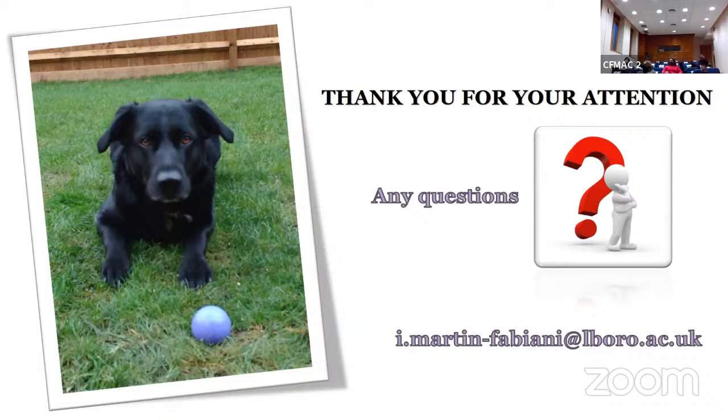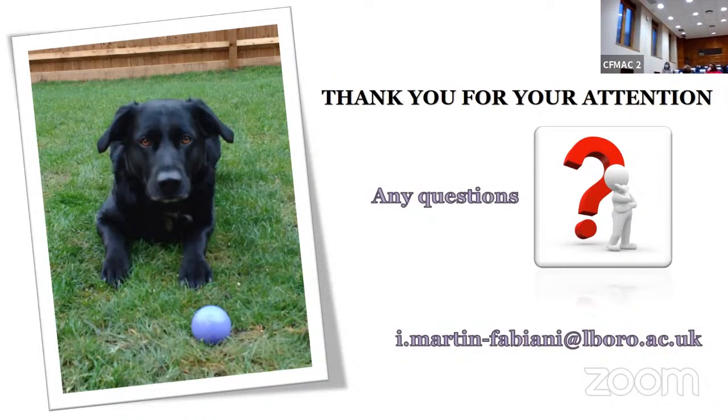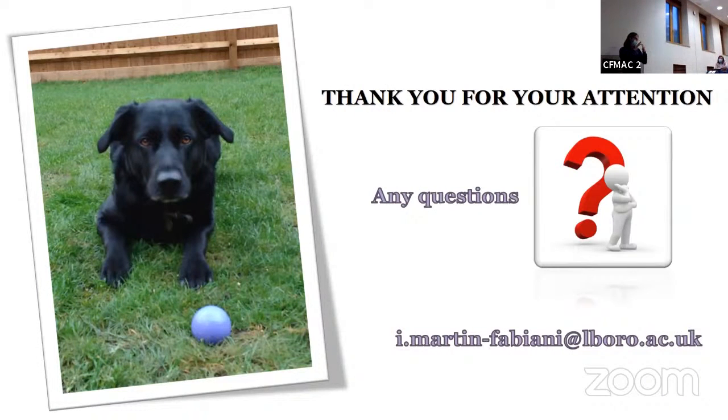Yeah. So we mainly do casting. Like I said, how fast that water interface moves is super important, because this process of size segregation only happens if it is fast enough to trap the small particles, which also happens when it is solid. We are in a lab which is more or less temperature controlled. So the medium evaporation rate is our standard: just leave it there and not do anything with it.